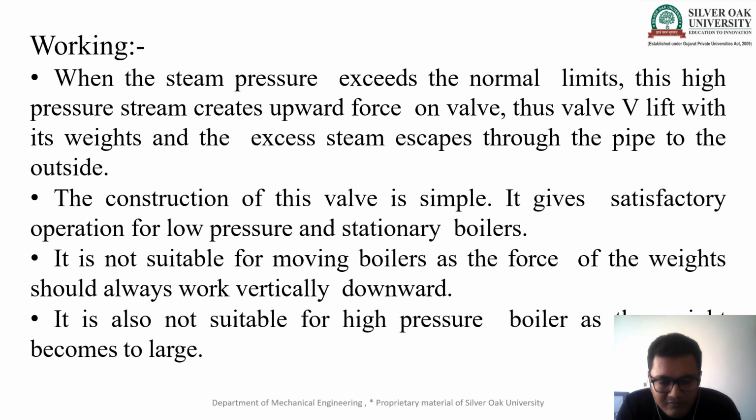If the working pressure is 60 but we move further, the valve will get deflected, the upward and downward pressure will get disturbed. Even if the steam is at the working pressure, the valve will lift and steam goes outside to the atmosphere.